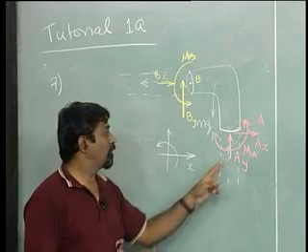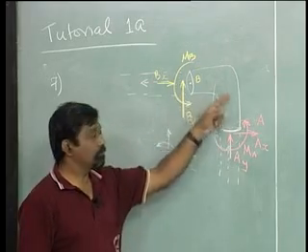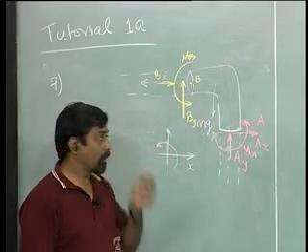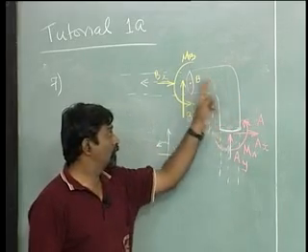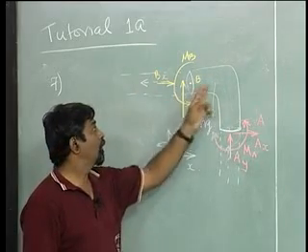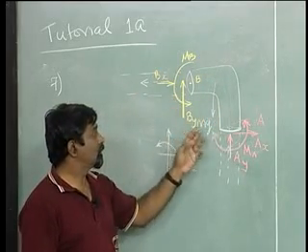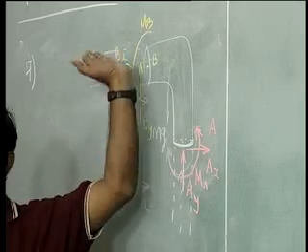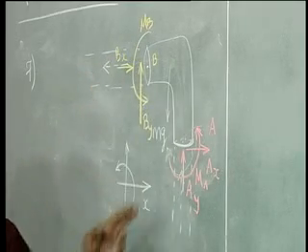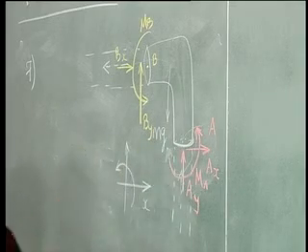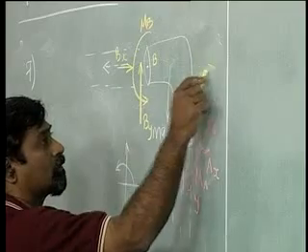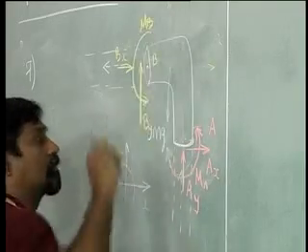What is left now is the interaction due to the water flowing from inside, right. As you can see, the liquid that flows from down to left in this particular case is changing in its momentum, the direction of this is changing, and therefore there is a change in momentum which will lead to two sets of forces, one on this surface and the other on this surface.